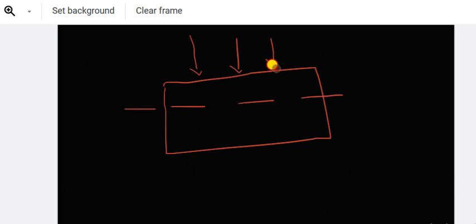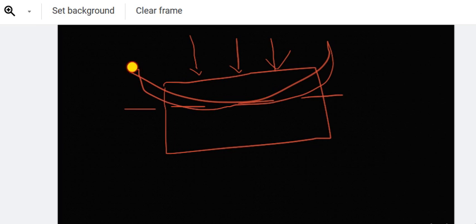So the beam bends. When the beam bends in this form, the decrease in shape and size here is nothing but the compressive stress. So the topmost fiber has the more compressive stress, and the bottommost fiber has the more tensile stress. Since concrete is weak in tensile stress, we will insert a steel bar. So this one is a steel bar.